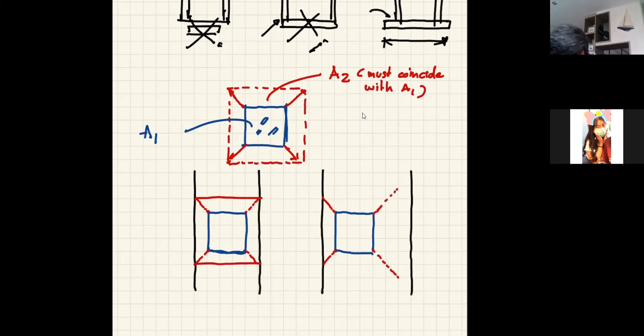You see, on the right side, I can go farther than on the left because I don't hit any barrier until this point. But remember that the area of the concrete that undertakes the load must coincide with the area of the plate. So that means this side hits the barrier first. So the area of the concrete that can take the load should be limited to just this.